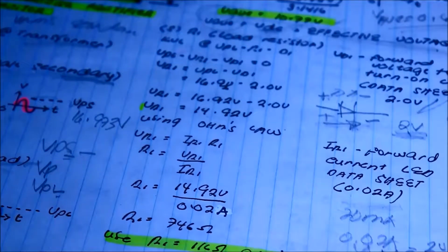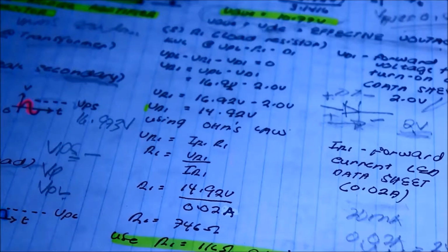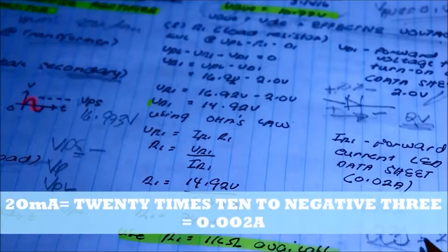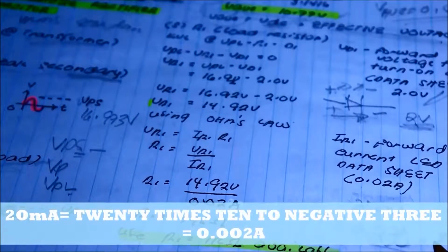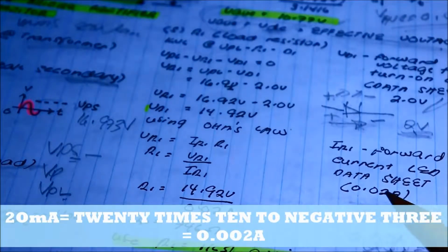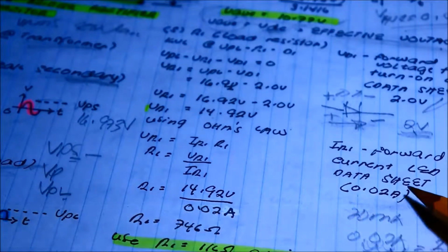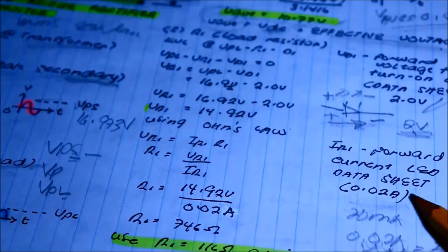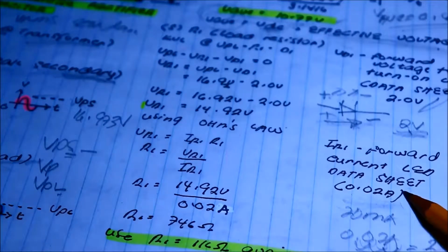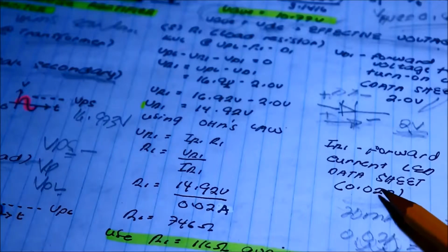0.02 ampere, just slide it to the right, times 3 milli, times 10 to the negative 3. This is mathematics. 1, 2, 3 becomes 20 milliampere. That is the current rating of the LED according to the datasheet. This 0.02 ampere is my standard value for computing the current that flows into the LED. That is the necessary current to turn on the LED.